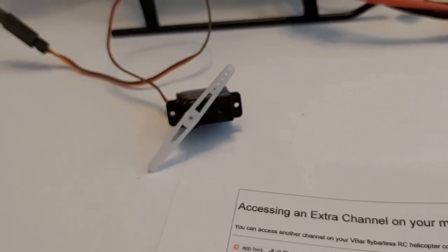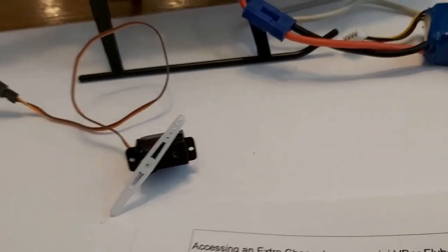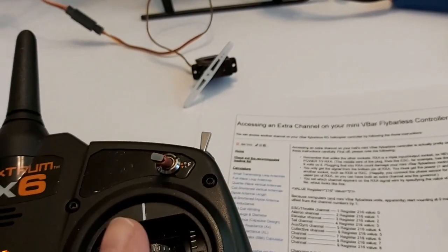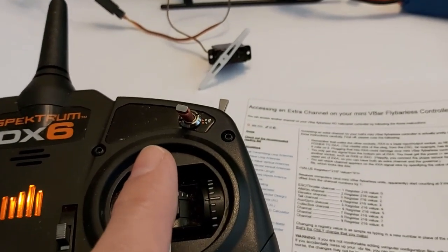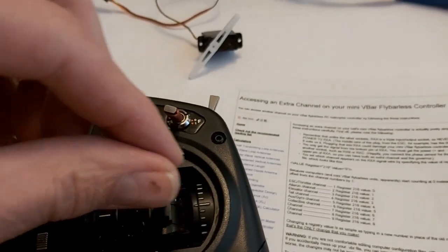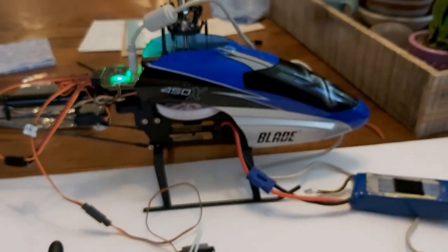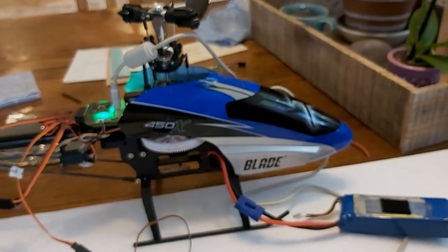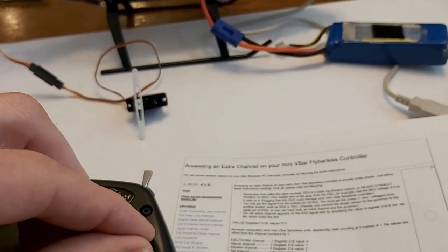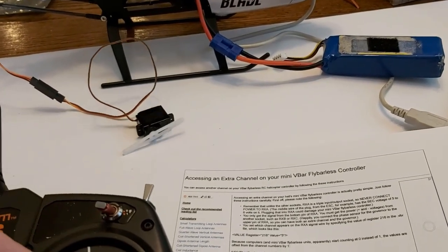And as before, now my auxiliary does nothing to it, my gear channel. But what's kind of cool, now if we look at this, and here's my aileron and elevator channel with the helicopter. Now if I move this back and forth, okay, you can see that as the swash moves, I also get a linear motion on, see, just on the servo, which is pretty cool.